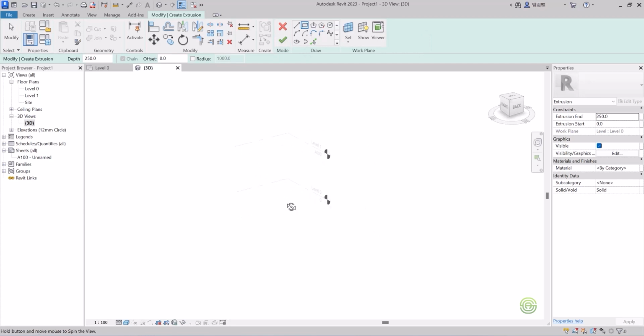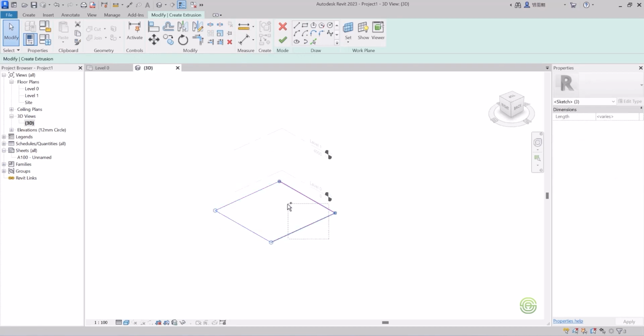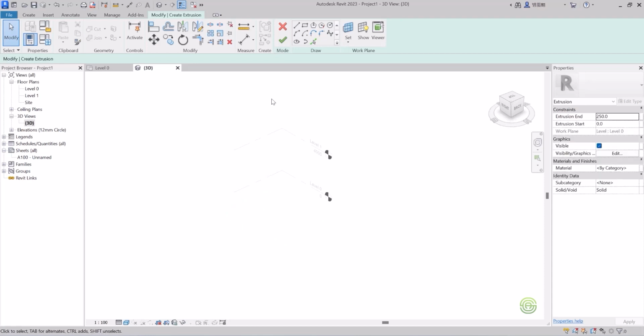Here press shift and move your cursor to orbit it. And now click and drag like this to draw a rectangle. Just draw a rectangle. I'll show you again. Just select this, press Control and select all the lines and press the delete button on your keyboard to delete this. Now to draw a shape over the 3D work plane, just select a tool. I'll select a rectangle here. Once you click on rectangle, just click and drag it like this. And now leave the click.